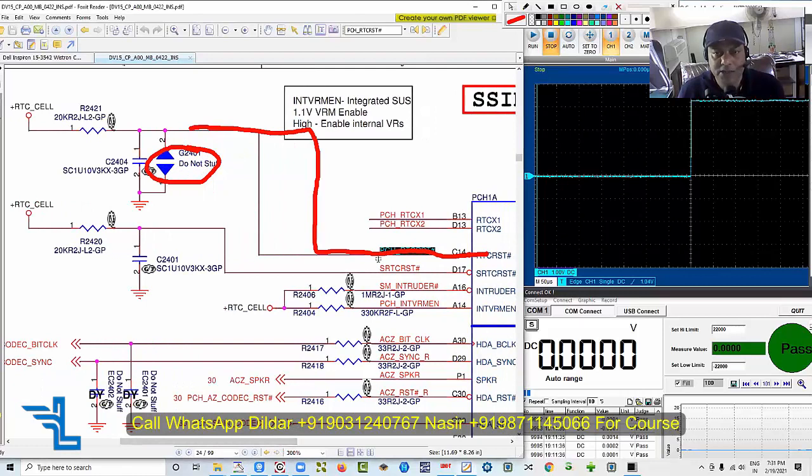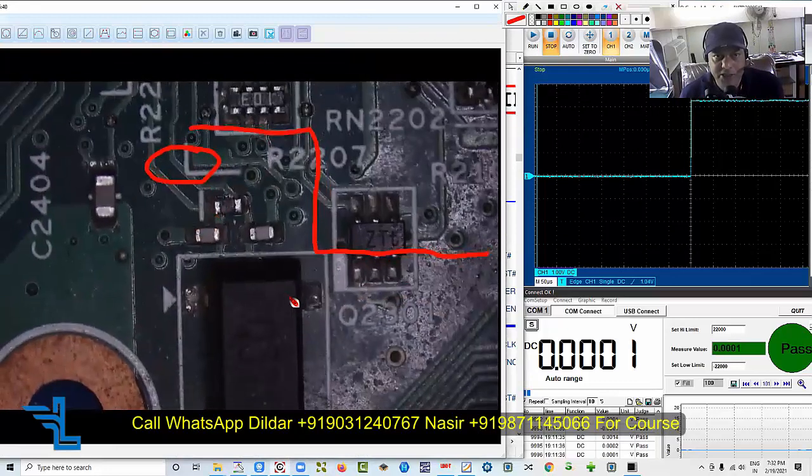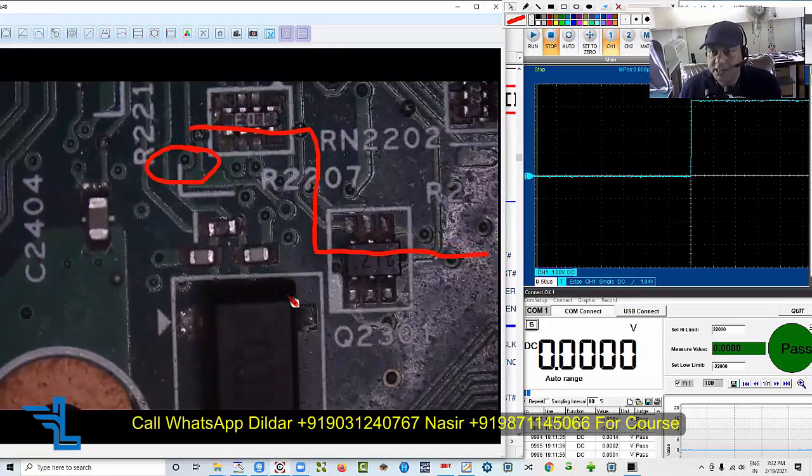And whatever is not written here, because we don't have board view, it is really a difficult task to find out that particular resistor and G mark and the R number and the capacitor. But we have to do it. Ultimately, the thing which I have already shown you, that was the 32 kilohertz crystal which is available here. Now let's make it sure once again that with the help of only coin cell, do we get that frequency or not. So now let me set my DSO on the auto mode.